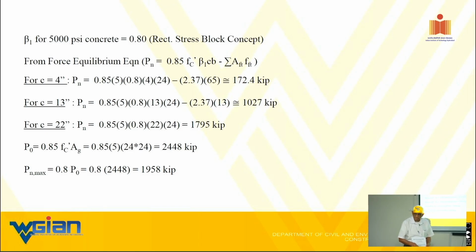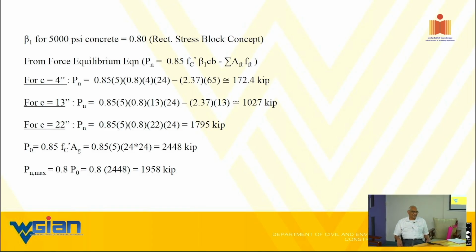There is a slight confusion, sir. The reduction factors are being applied at many steps. The design is to be kept on the safer side, as an engineer. That's why we are doing the constraints. According to the Indian codes, the reduction factor is usually implemented at one or two steps. They combine all the types of reduction factor in one number and multiply it once. But that leads to a higher penalty, so you get a more conservative design.